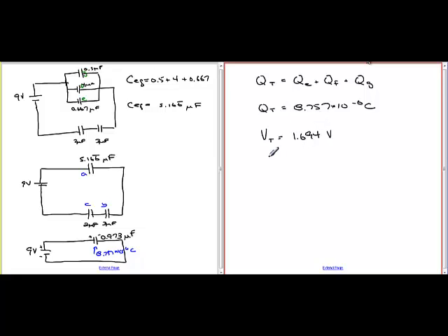We can then calculate the capacitances for each one of those. We can calculate the charge on each one of these capacitors, again, using the definition of capacitance. Capacitance is charge divided by voltage. What we're trying to find is Q. Q is equal to capacitance times voltage. We're going to use this to check our results, but we don't need that number. It's going to fall out automatically.